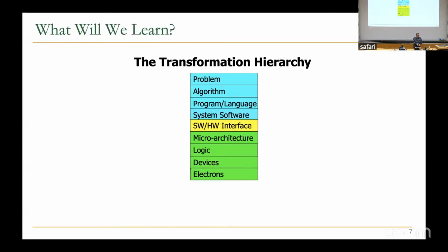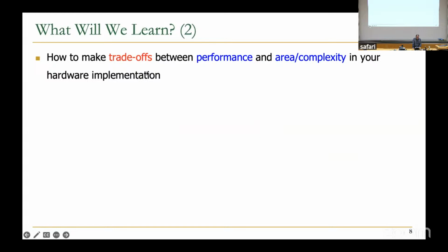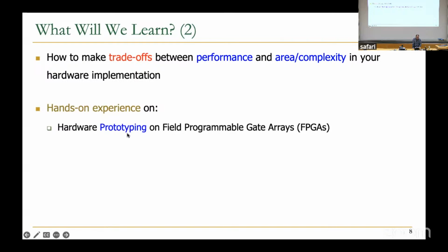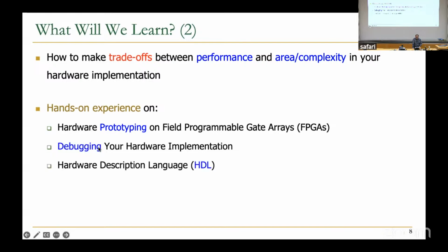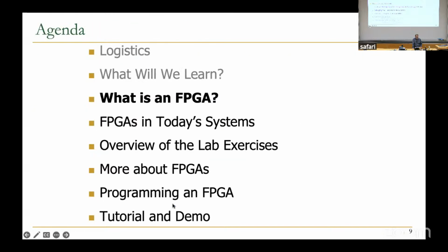So what we will learn in these lab sessions: we're going to see the transformation hierarchy, and we're going to understand the software-hardware interface, microarchitecture, and logic, specifically in labs. And how to make trade-offs between performance and area complexity in your hardware implementation. There is hands-on experience in hardware prototyping using FPGAs, and debugging your hardware implementation using a hardware description language, HDL, specifically Verilog, how to use it, this hardware design flow, as well as computer-aided design tools, short as CAD tools.